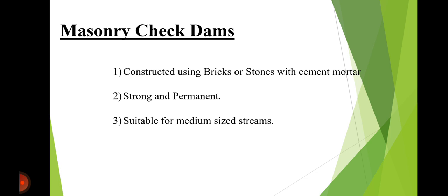So gabion check dam, made of wire mesh boxes filled with stones. It is strong, flexible and durable, suitable for moderate to high runoff.